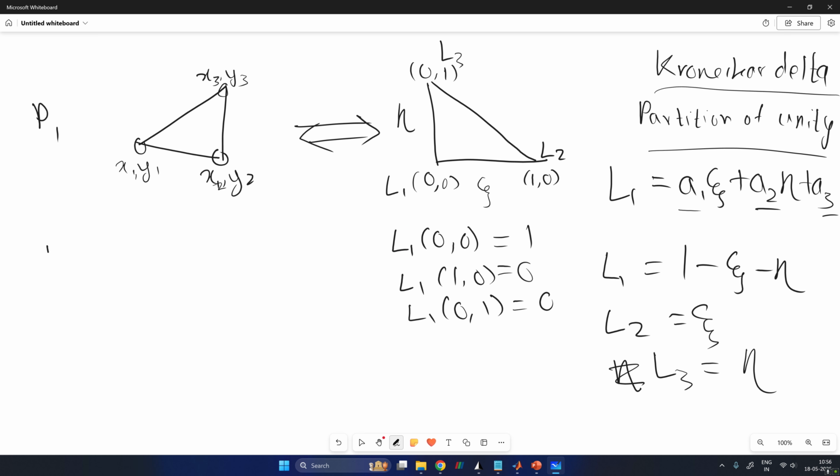In the case of a quadratic triangle, you have three extra nodes at the mid edges, and we'll place them exactly at the mid edges because we are dealing with simple Lagrange elements, not any complicated elements.